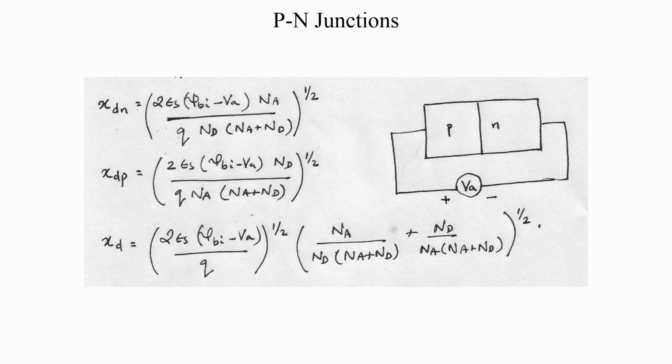So when we take it out of equilibrium, let us do so by applying a voltage. We are going to apply a voltage across the PN junction, and the voltage is being applied in a manner where the plus is toward the P side, which is at a higher potential compared to the N side. If VA is greater than 0, that is, the voltage on the P side is greater than that on the N side, then the device is said to be in forward bias.